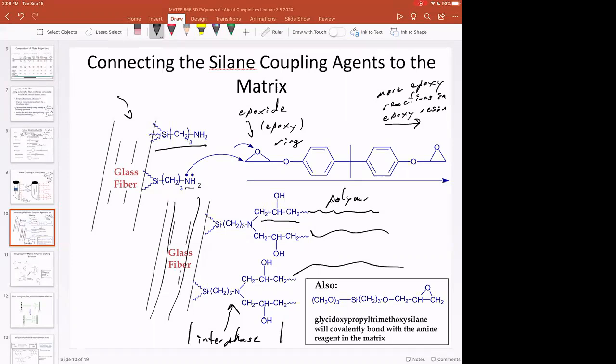And so usually when you design a composite, you want as good a compatibilization between the two phases as you can get, which means 100% coverage or optimized coverage of coupling agent. And then you tweak the properties of the composite by the filler matrix ratio, or by the choice of maybe a polymer that has a little bit lower modulus or a different type of fiber. And so that's really your design space.